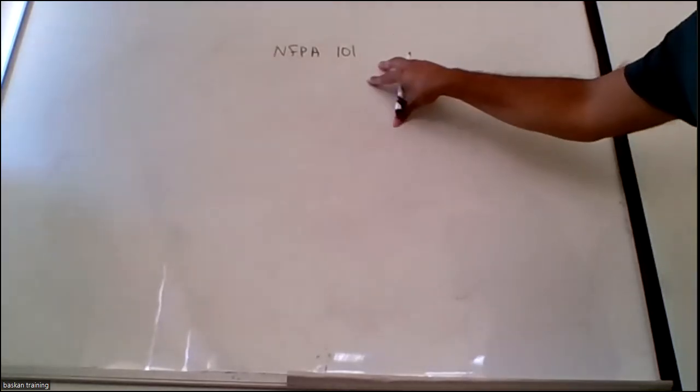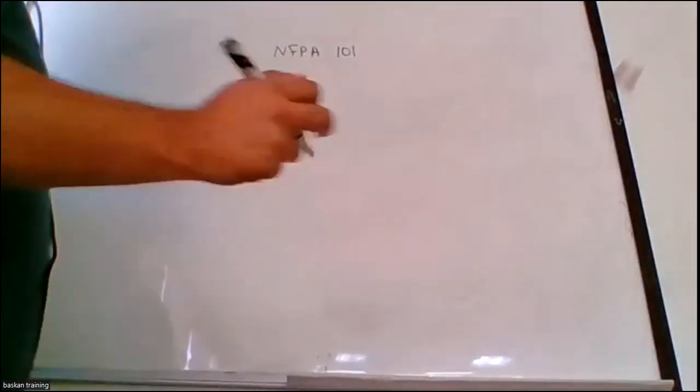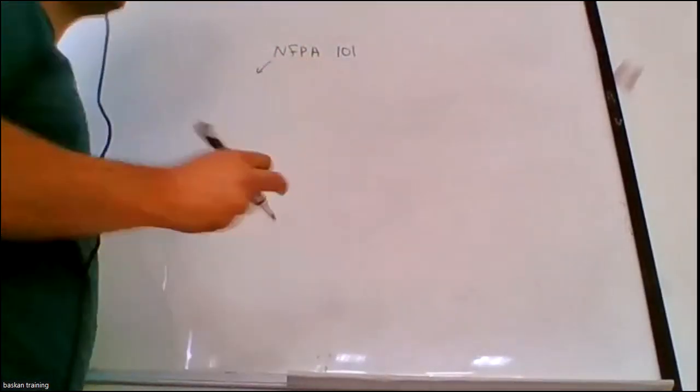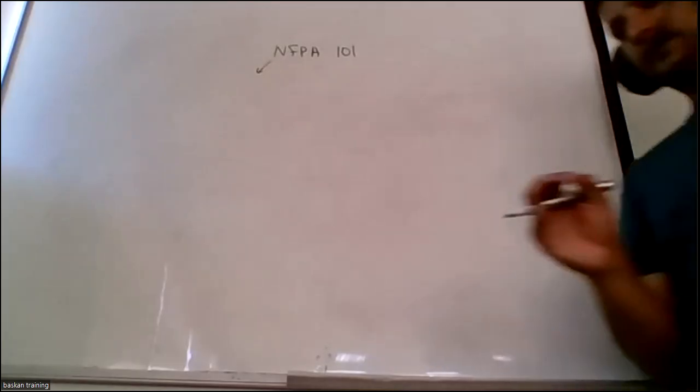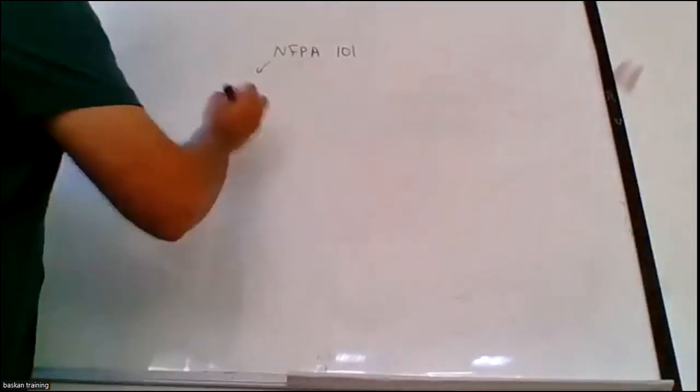The first thing about any fire protection device is the evacuation and life safety of the people. That is the first primary goal that we always want to achieve. NFPA 101 has some very basic guidelines, that there should be enough means of egress available for the people, unobstructed means of egress.